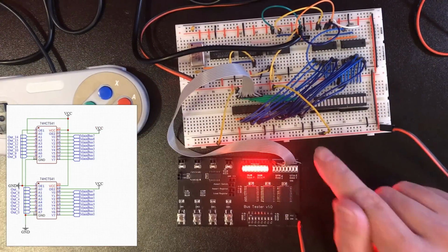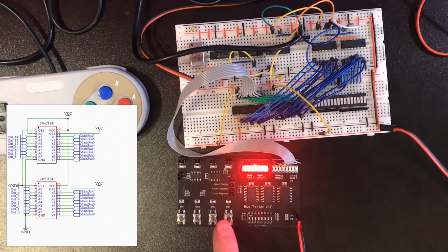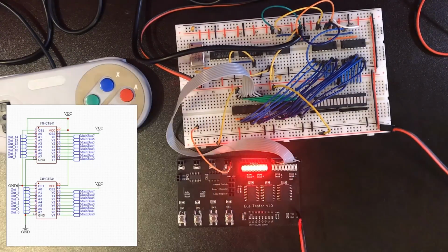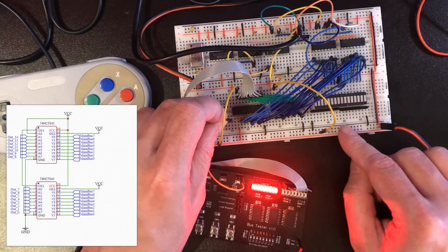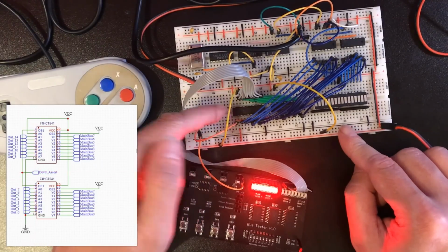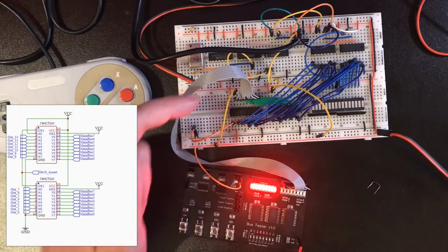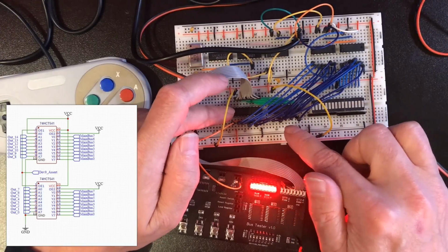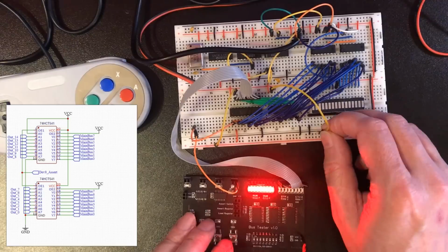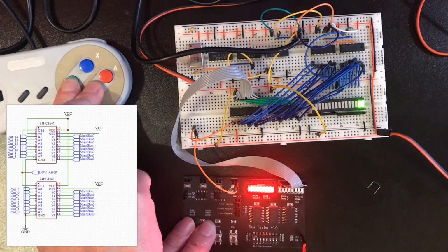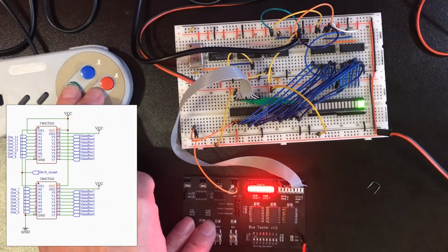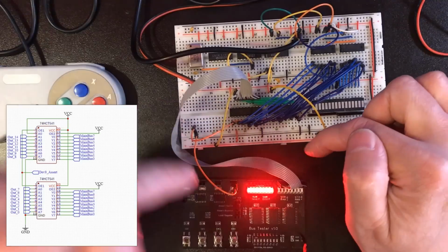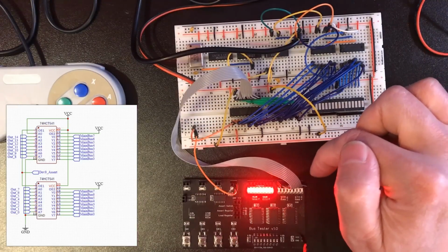So now we need the circuit to actually select one of these based on a read signal. So first thing is we're going to use the read signal as an active low on the output latches. So now it's only possible for those to put the output onto the main bus when the read signal is low. Okay, that's good, that's working in exactly the way I'd hoped. And now what we need is a flip-flop that is going to change state each time we select it.